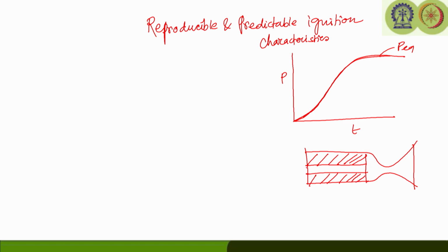Now, if you put this thing, this is the igniter. So, let us say it will have some pyrotechnic igniter. There will be some ignition coil here. The igniter will create some ignition plume that will heat up the initial propellant surface and start igniting it, and that will fill up the port volume of the grain with the combustion gases.